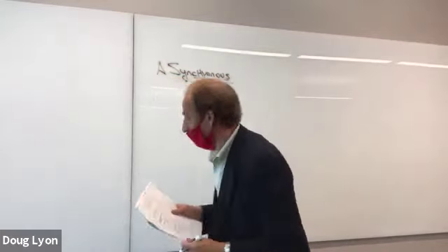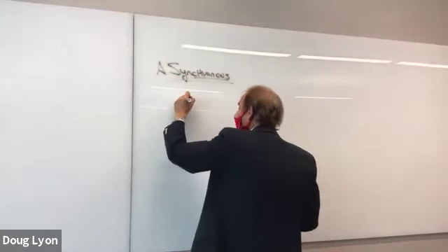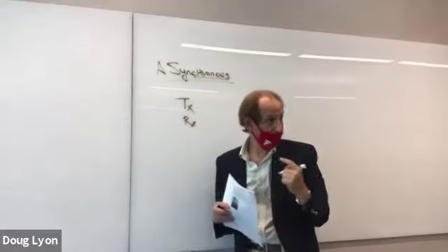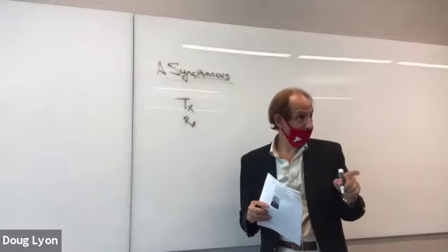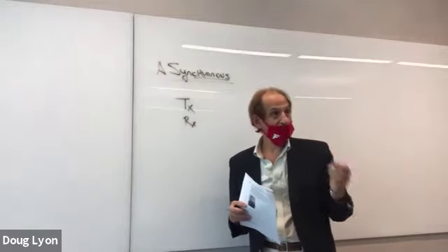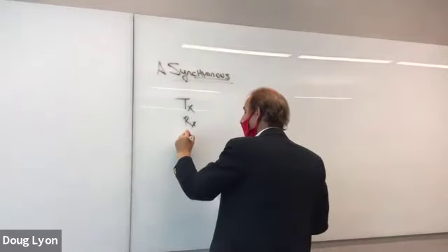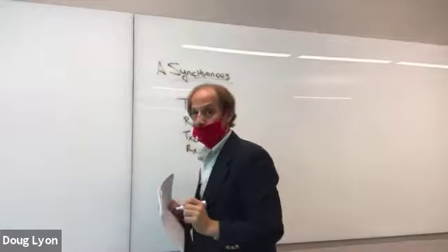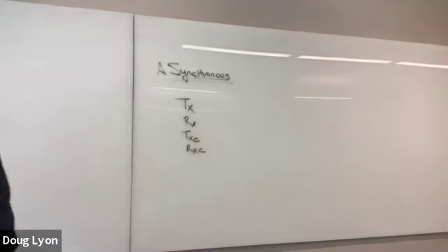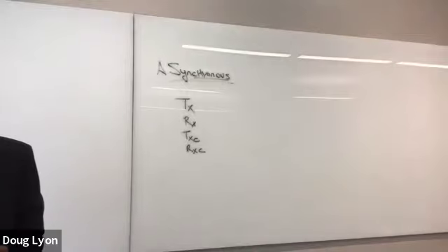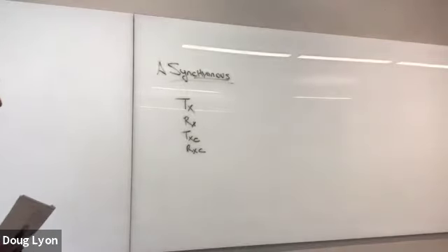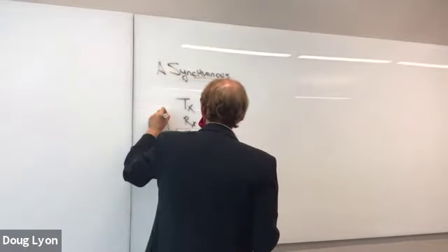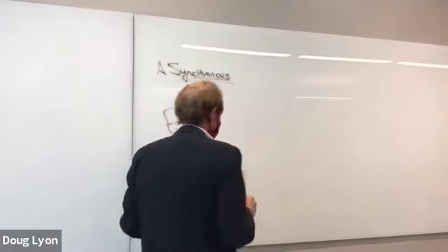When you have a serial communication protocol, you can have a transmit line and a receive line. The transmit line will transmit binary data, and the receive line will receive it. But if you want it to be synchronous, then you're going to have a transmit clock and a receive clock. If you have synchronicity in those clock signals, you can run at much higher speeds. But an asynchronous system will try to embed the clock signals directly into the transmit and receive lines.